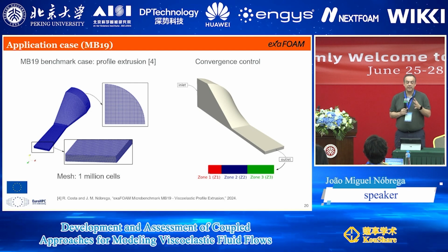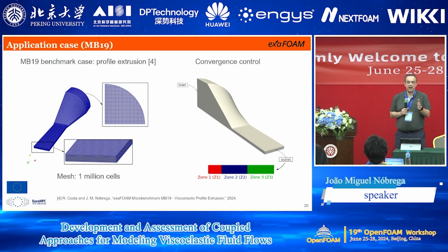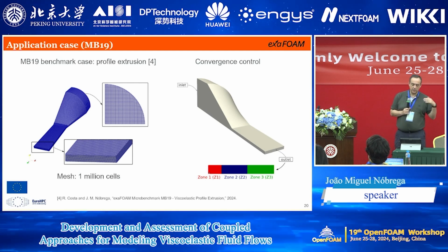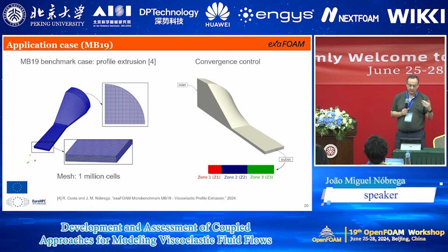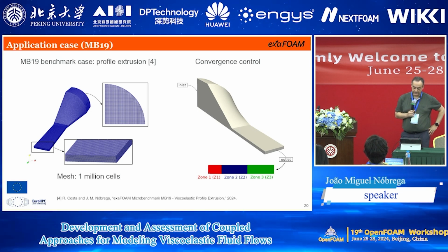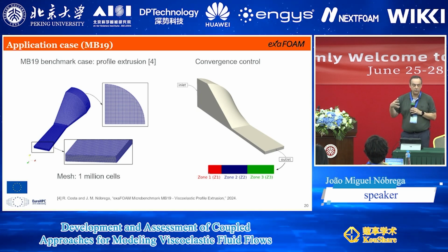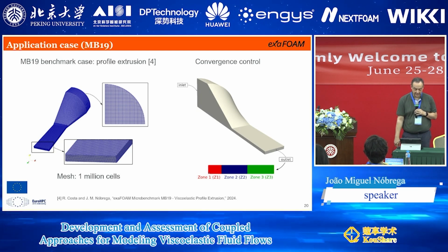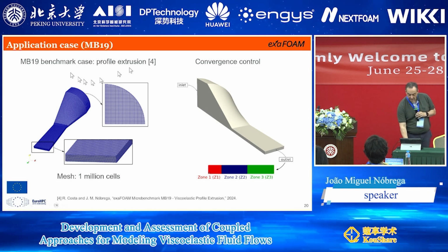But the way the residuals are defined in different approaches is not consistent, so it's not a good approach. Instead of controlling convergence through the residuals, we control the convergence through some relevant calculation variables, in this case inlet pressure and the outlet flow distribution in 3 regions.